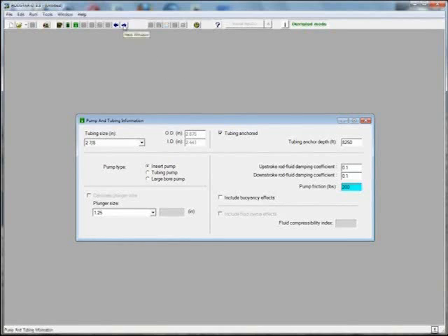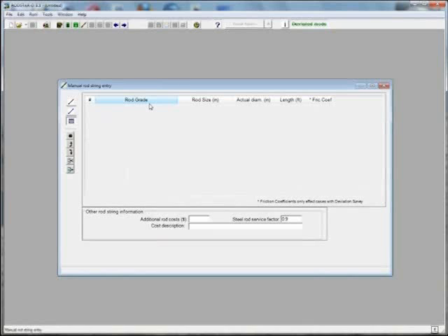In addition, of course, in a deviated program you have the buckling tendency plot, which tells you how likely you are to buckle. The include fluid inertia effect option is grayed out because this is not a group 2 well. Group 2 wells are shallower, high rate wells, typically 3,500 feet or less, with 2 1/4 inch plungers or larger. Obviously in this case we're not in that range, we are deeper and we have a smaller plunger, so this option is deactivated.